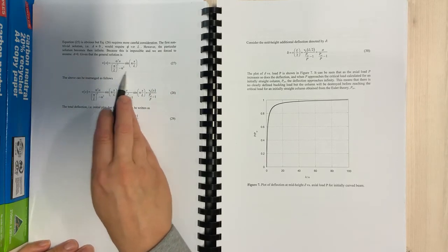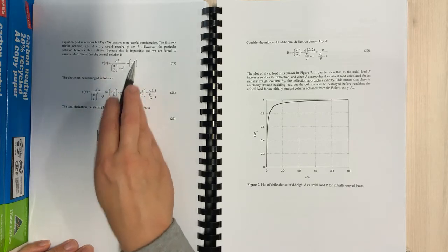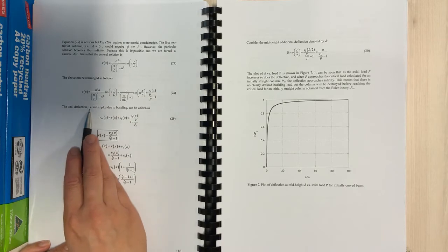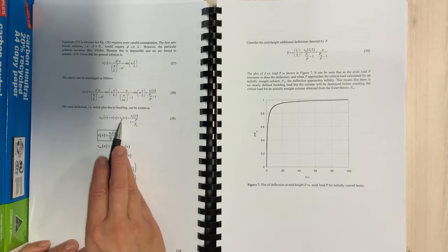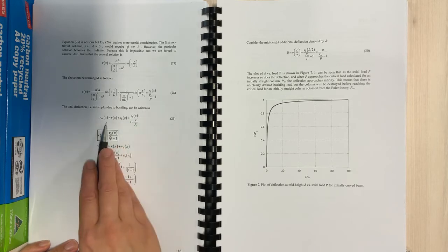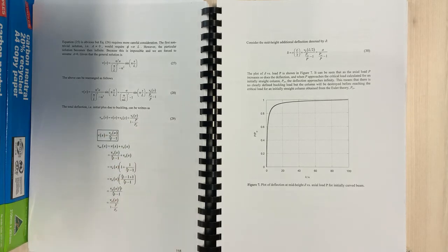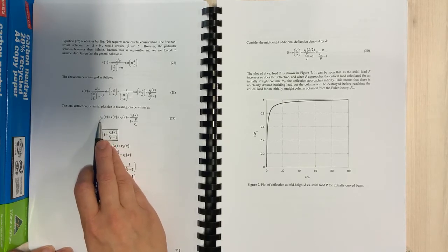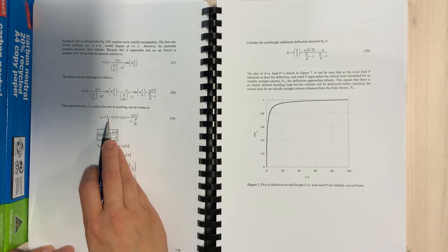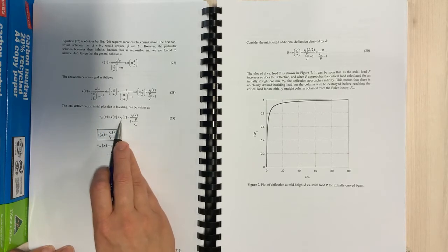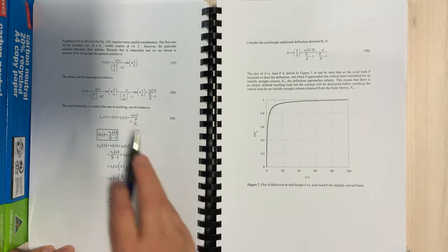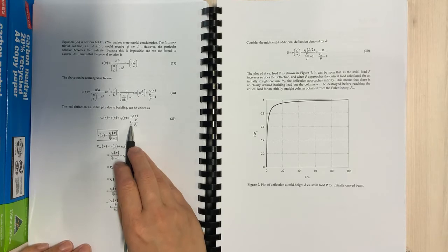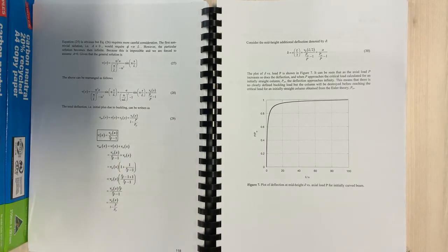So given that the general solution is going to be in this form here, rearranging it into this form here, the total deflection, i.e. the initial deflection, which we would see there, can be written as this function here. So V total of x, which is the total displacement, is equal to V of x relative to the initial deformed shape, and that comes out quite nicely as V naught x 1 over P over PCR minus 1.